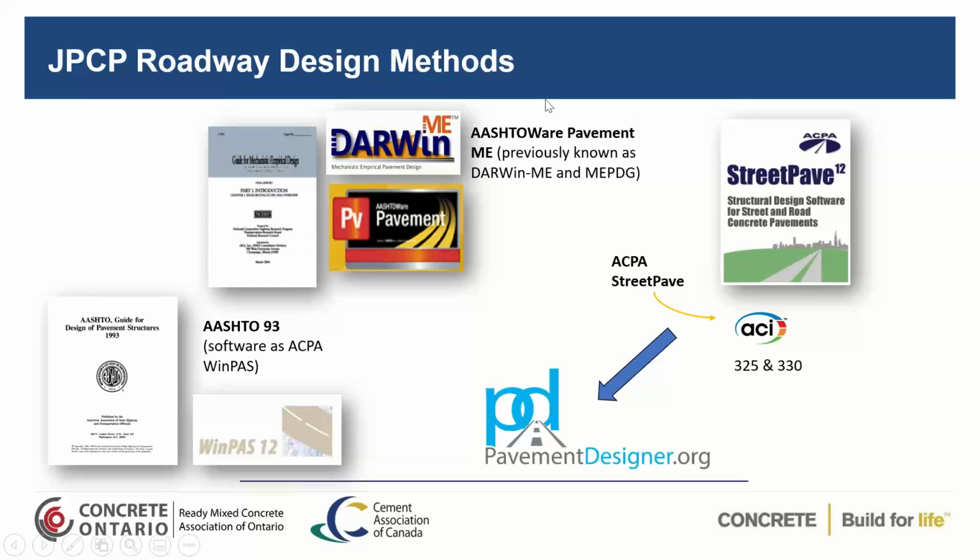Then you've got the most sophisticated program, the Darwin ME. This is the much more expensive program, but it actually allows you to go in and analyze those things that I've mentioned, the coefficient of thermal expansion, the Poisson ratio, a lot of detailed data on the concrete or asphalt side. Then you have StreetPave. StreetPave actually took the original PCA mechanistic design procedure, fine-tuned it, and then used the empirical information from the road test to help calibrate the model to give you a very good and accurate concrete pavement design tool, but not as sophisticated as Darwin ME, AASHTOWare ME.